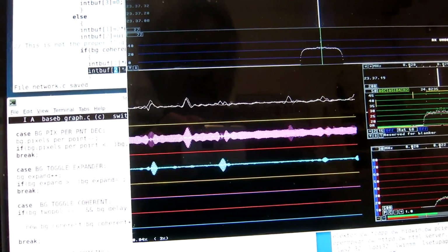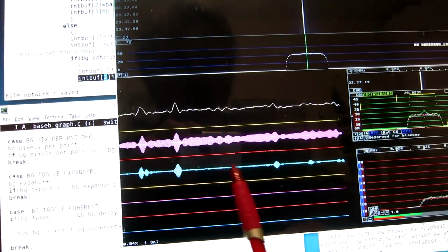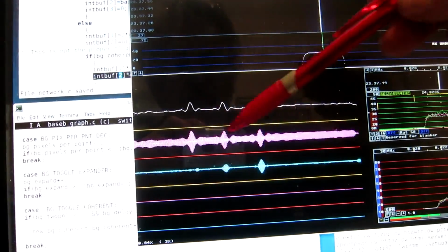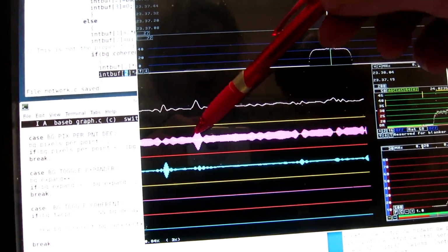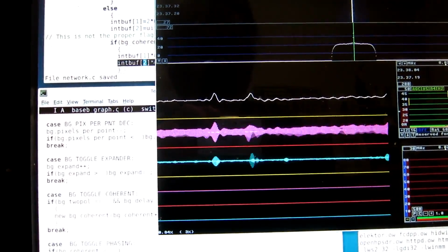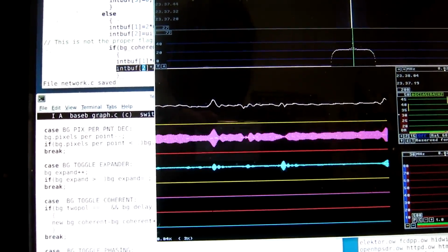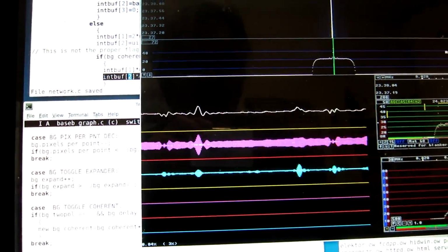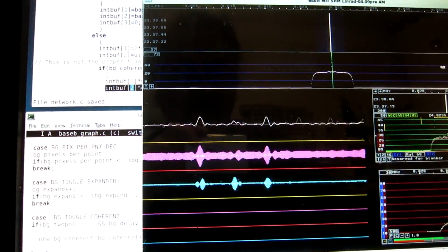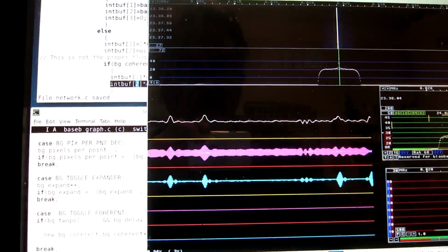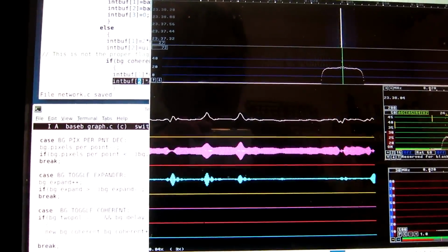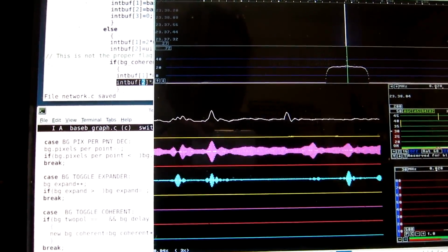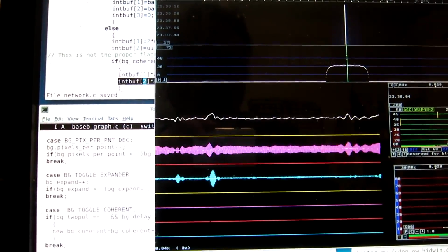So what could be possible is to use the information about the pulses to perhaps subtract something, or at least control how to reduce gain to do a better noise blanker. And I think this is what the vectorial blanker in Perseus is doing. It's using the information that is recovered as the out-of-phase combination of the 2 sidebands of an AM station to correct for the pulses.